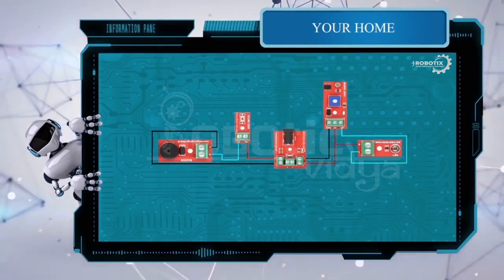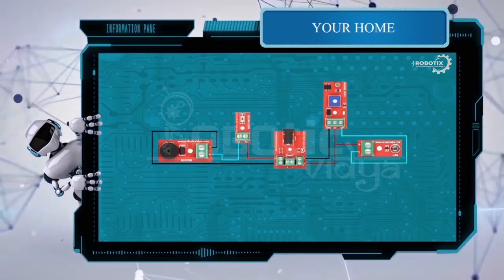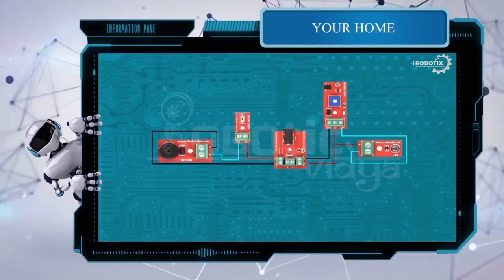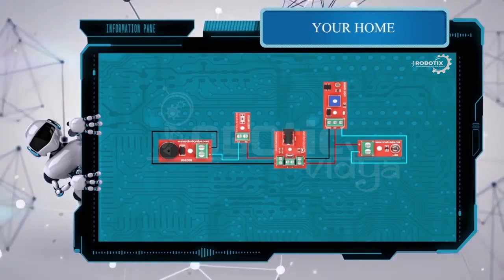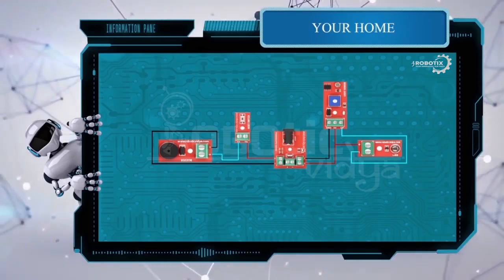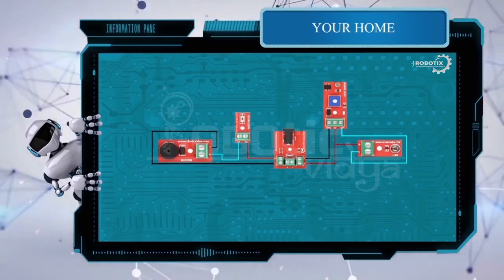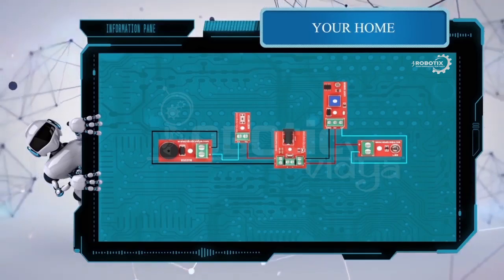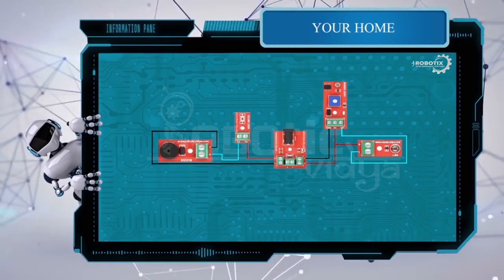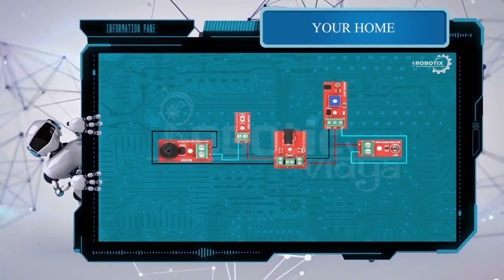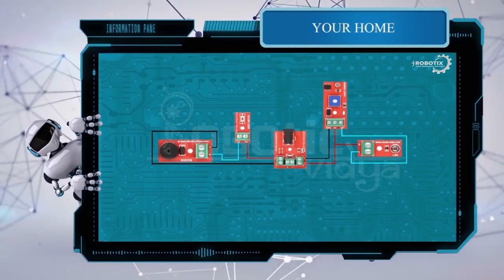The output will go to the negative of your LED, and the positive of your LED will go to the positive of your power supply board. Now remember, you can connect 2 wires into the same hole, just like how we did in our door open detection experiment. Finish your connections, so we can proceed to the next one.